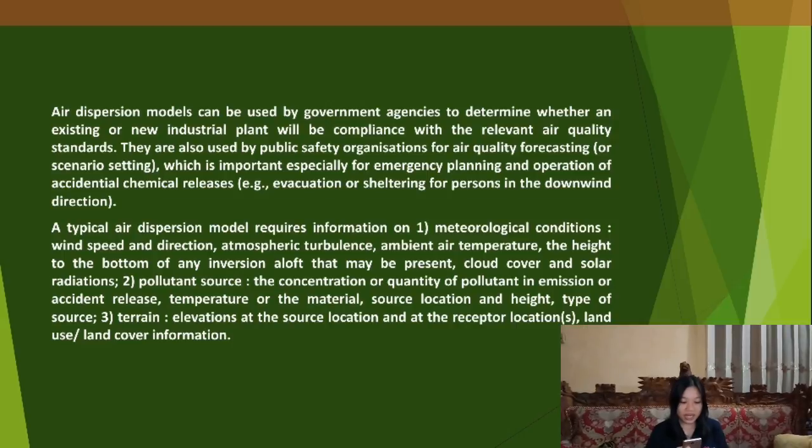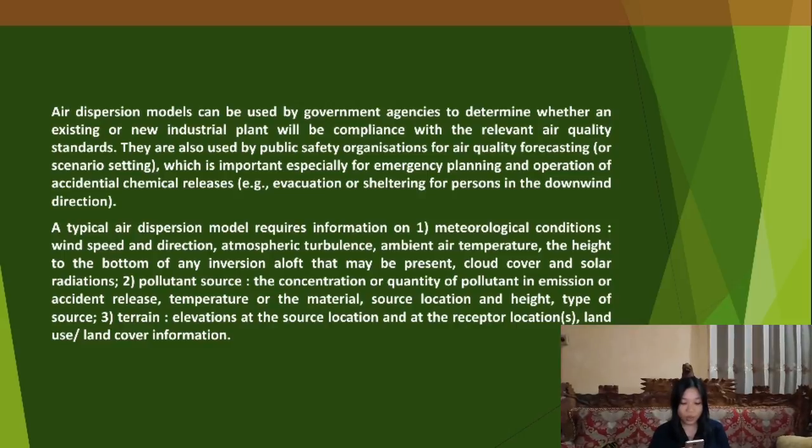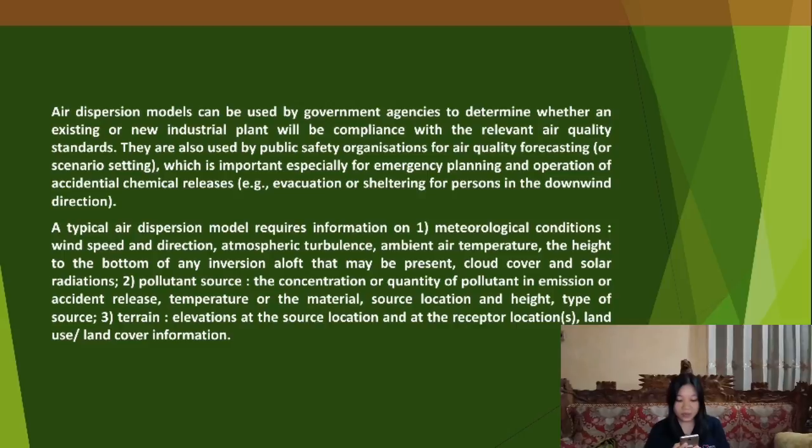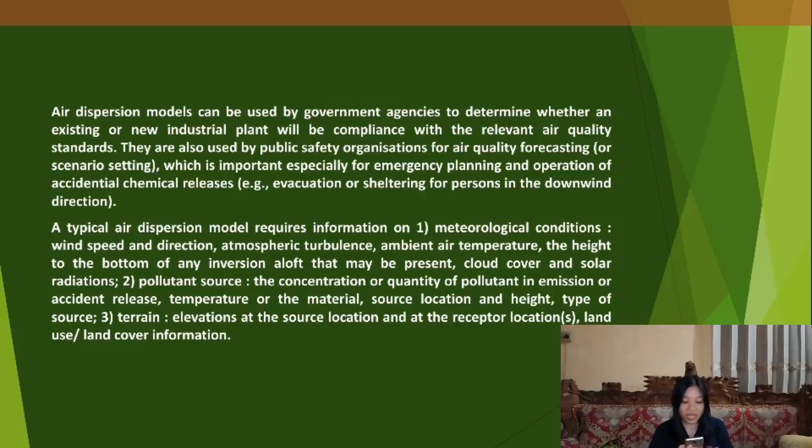A typical air dispersion model requires information on 1. Meteorological condition, wind speed and direction, atmospheric turbulence, ambient air temperature, the height to the bottom of any inversion aloft if they may be present, cloud cover and solar radiation. 2.